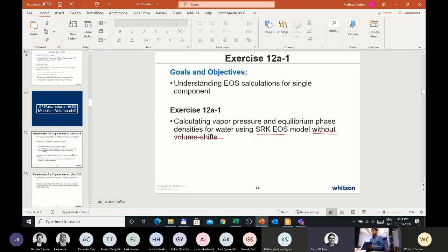If you have to use compositional equation of state modeling and want to get the compressibility of the system and the recovery of the system right, from high pressure down to, let's say, saturation pressure, the only way to do that is to correct the total system compressibility, meaning rock, water, and hydrocarbon. Hydrocarbon is going to be wrong.